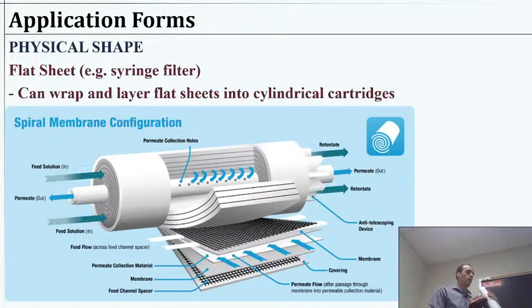And even this would work if we just had one of them. But now we have a system where we can plumb it, so we can pour water in one way and pressurize it. Any water that passes across one of these can then travel inside that spiral because we've added that spacing material. So at no point can water just find the other side if we do it right. Water has to go through the membrane to find the other side.